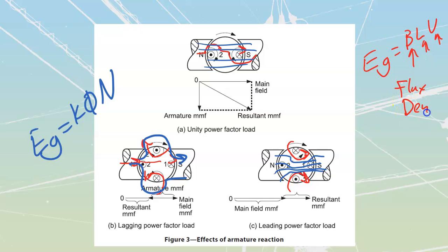And flux density just talks about the fact that it's the same number of lines of flux, we've just grouped them closer together. This describes a much greater amount of flux density. We've mashed them together, like in the analogy of using that tree shredder, we've grabbed them and shoved them all onto the inside over here. So my flux density has increased, same number of lines of flux, but they're closer together where they cut through these conductors. Therefore, the amount of voltage generated is going to become larger off of these as well.